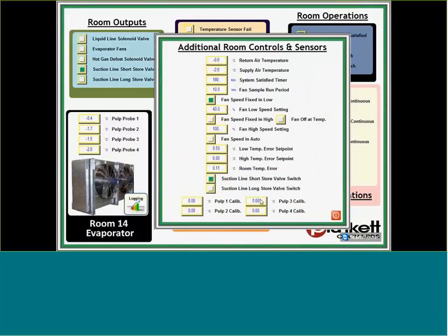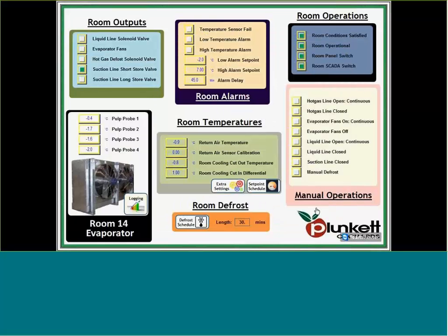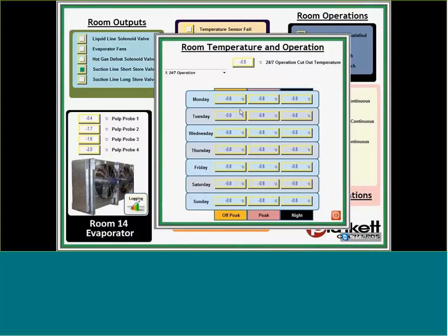A pop-up page for people that are interested in further stuff. A lot of that's got to do with energy saving options and some additional calibrations. We also did some set point scheduling on site. This was an energy saving feature that you can select through InduSoft. You get a nice little drop-down box there. Each one of those options populates more options on the screen there, and that's all done through scripting.